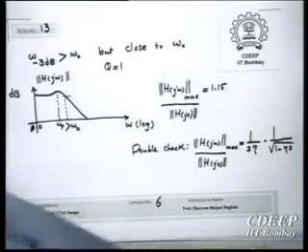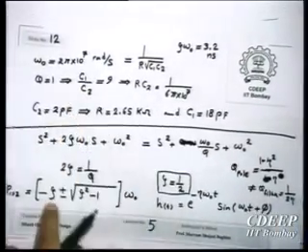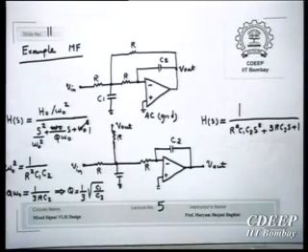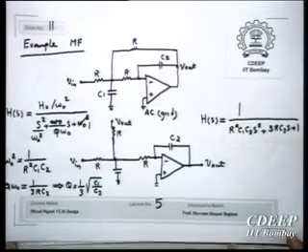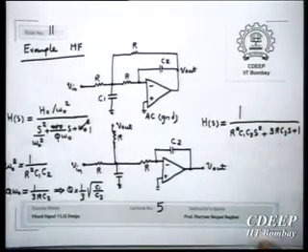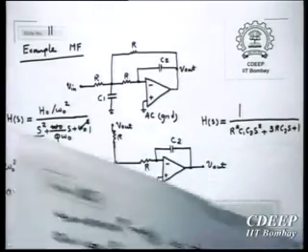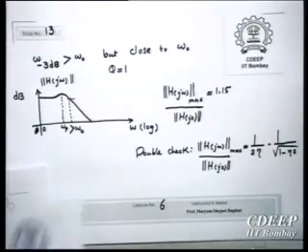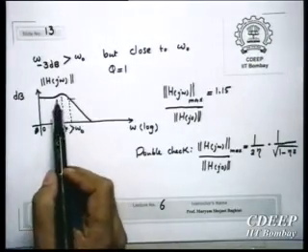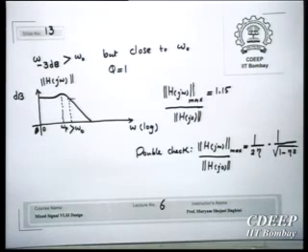Okay, and now how will the parameters change? Here we are able to stabilize Q because it's a ratio. But we are not able to control RC, because R and C both will change with the process. Because of this, the characteristic of this filter will be like this. Q will be constant, but it will shift to left or right due to process variations.